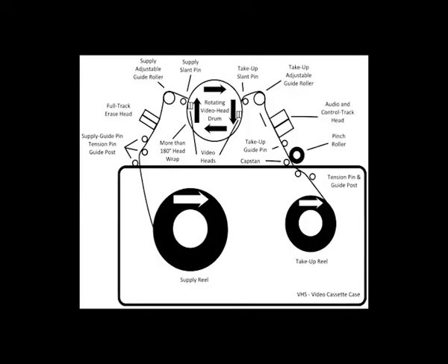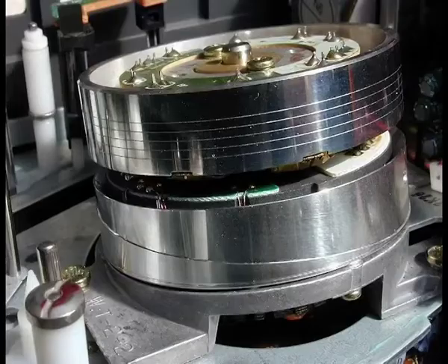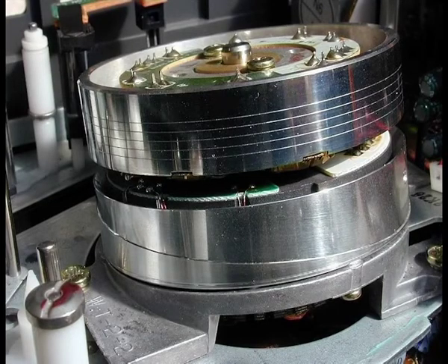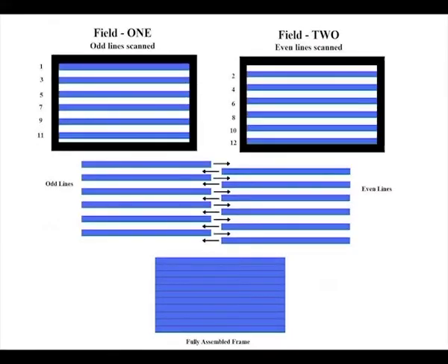The analog video and audio signals are written to tape by a spinning recording head that changes the local magnetic properties of the tape's surface in a series of long diagonal strips. Because the head is canted or tilted at a slight angle compared with the path of the tape, it follows a helical path which is called helical scan recording. As illustrated in the figure, each strip represents information for one field of video frame. A single frame is made up of 2 fields that are interlaced.